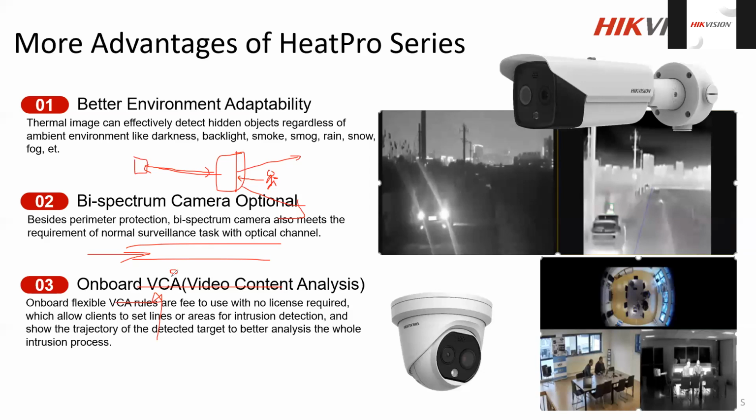In the traditional system, what we have is the smoke detector. If the smoke comes out, our camera can pick it up. Number one. Once the fire starts, whatever is around the fire area also absorbs the temperature, right? So very soon, the surface temperature will also increase slowly, and actually it will happen faster because fires spread faster, right? As soon as the surface temperature increases beyond the threshold that we configure in the camera, we get the alert.